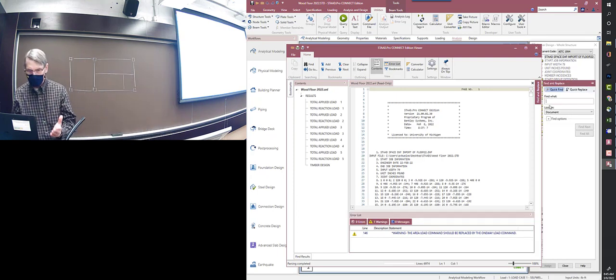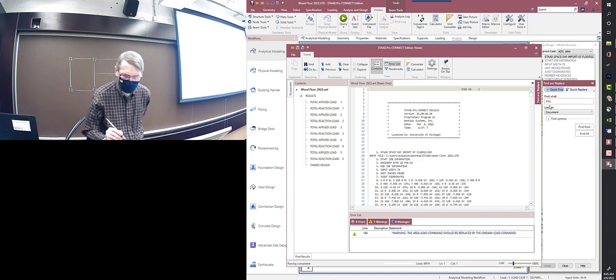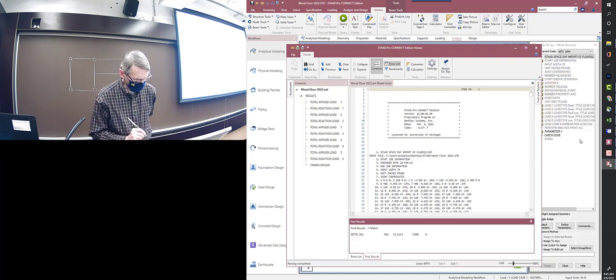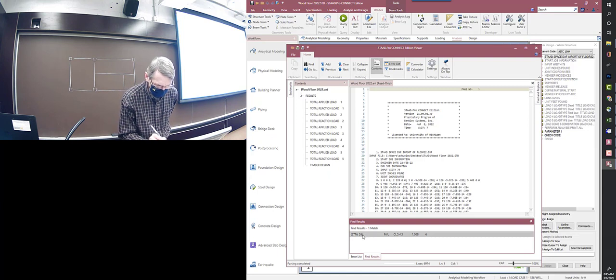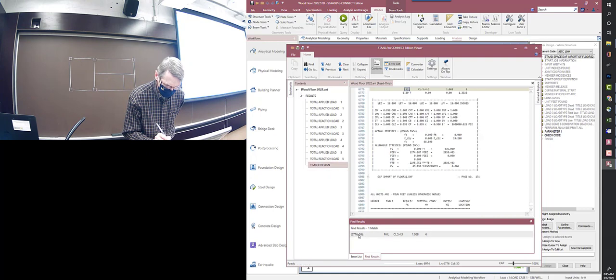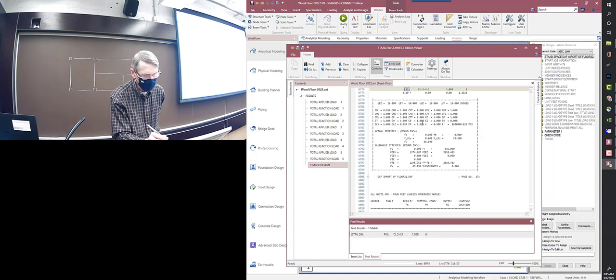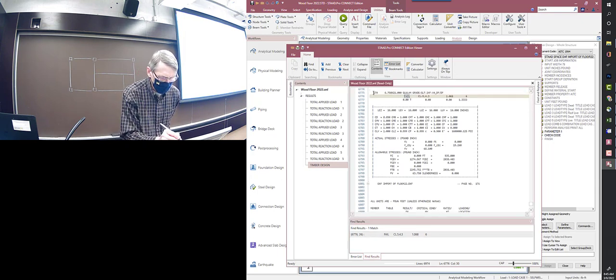If one's failing, it'll have the word fail on it. So that would be a nice term to search for. We could find all. Why not? Okay, lucky us. There's only one that fails. And I think if you click on this, you'll jump there. There it is. The one that failed is member 179. So I was almost there. 179 we'll have to go back and look at, but you could see how it fails.